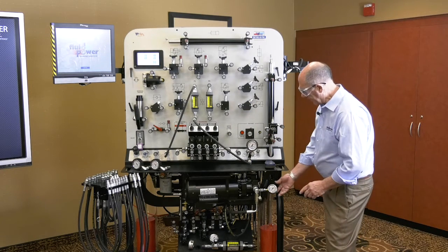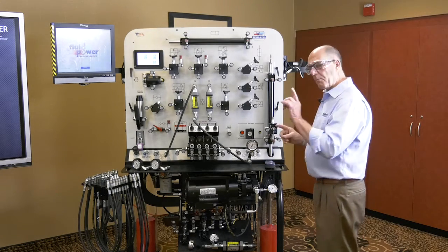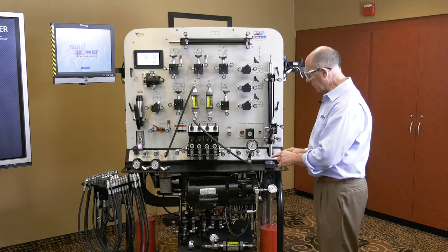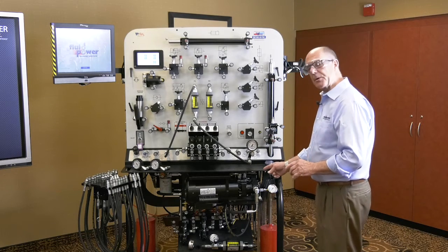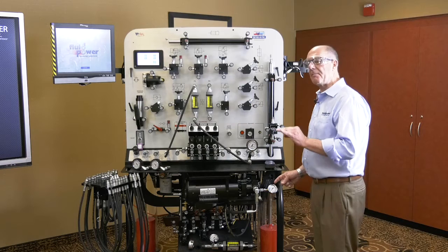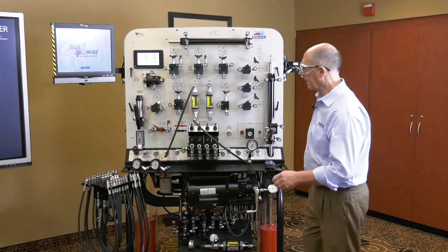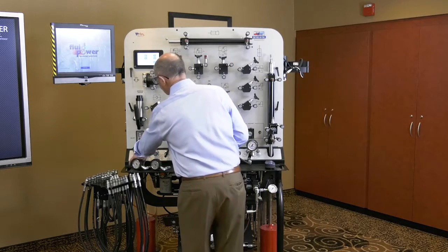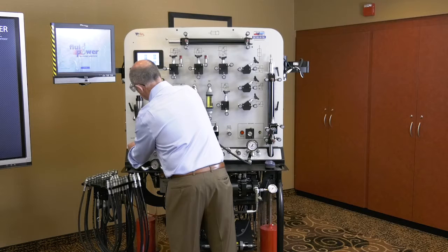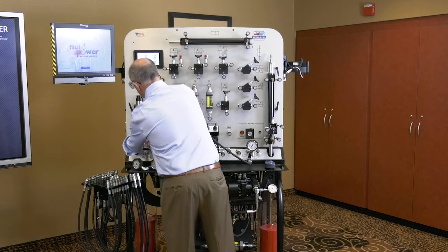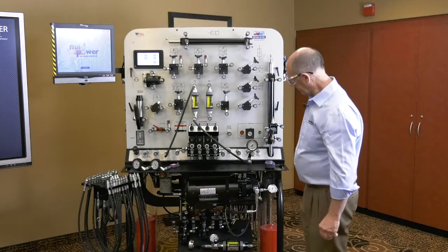What I'm going to do is start it up and determine what the point of reference is for this pump's inlet restriction. Bear in mind that this is an axial piston pump, and according to rule of thumb, the maximum inlet restriction is 4 inches of mercury. So I'm going to remove the lock from the machine because it's been safely locked out. I'll remove the lock from the machine, and then I'll turn it on.